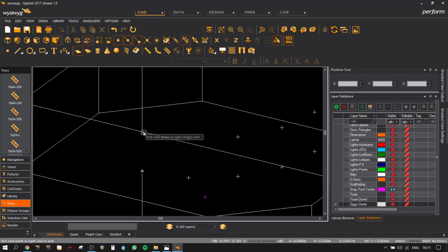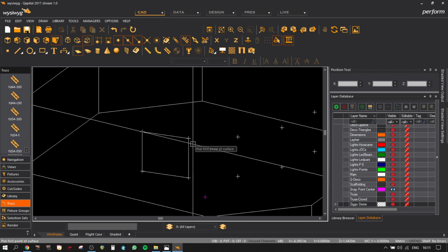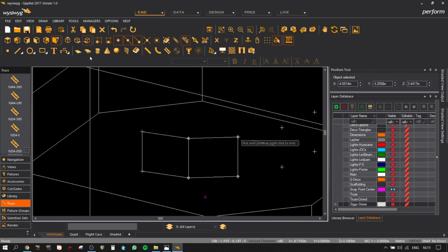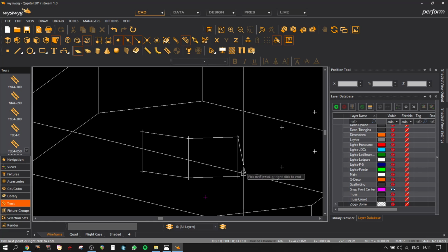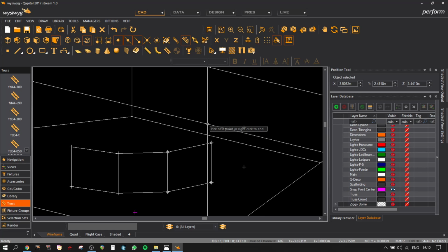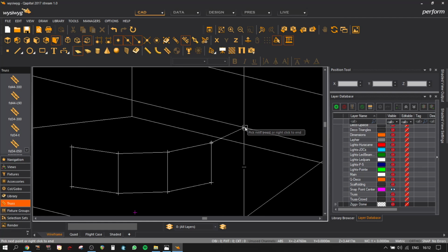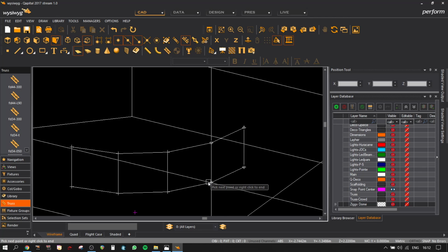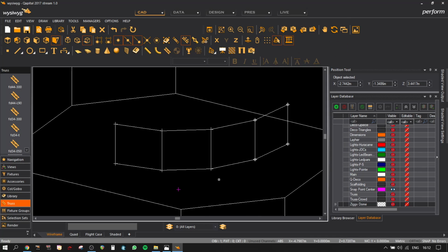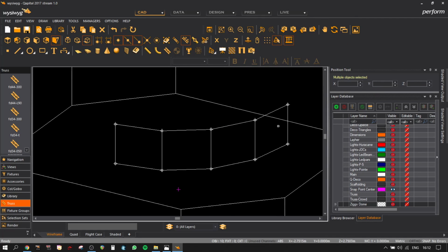Right, so now I'll just go in here, create my surfaces to make it a circle. The more snapping points you use, the smoother the curve will look. Since it's all black, I don't care. So now let's select all snap points.